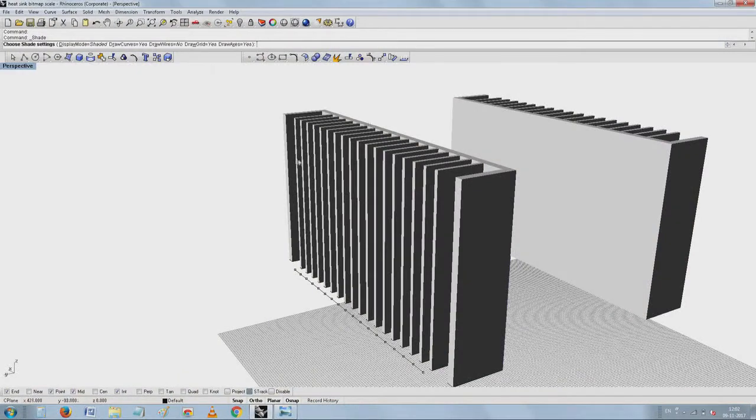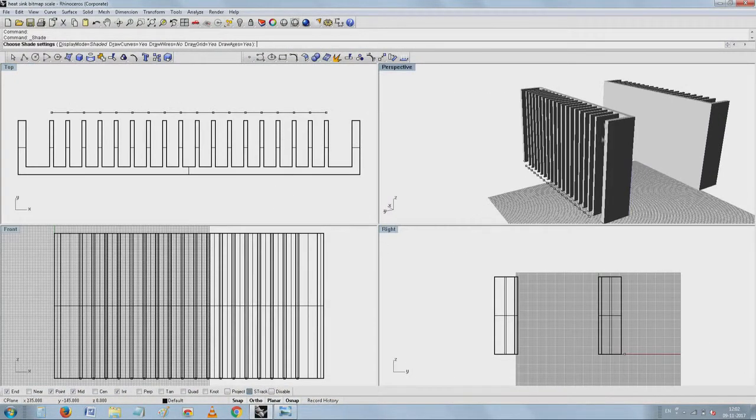Similarly, if you take the height, it goes in terms of U's. 1 U is 44.45 and so on, and then generally 3 U. Typically a 3 U rack will be 132.5, and this is a good starting point for a rack with heat sinks in the vertical direction on the face back. Now, while this is one of the conditions, it is not the only way you can do it. It is very much possible for me